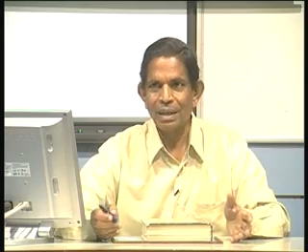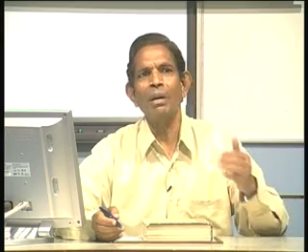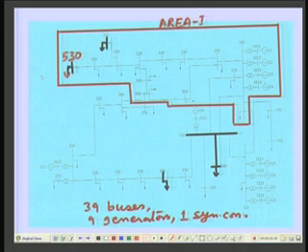That is, you assume that bus number 530 is a PV bus, and perform the load flow analysis, and then compute the reactive power required at this bus to maintain the voltage at that level. Now, this exercise has been conducted for 4 different buses in this system. The buses identified are bus number 160, bus number 200, bus number 510 and bus number 530. That is, for the complete system under the normal operating condition, the QV curves are to be generated.